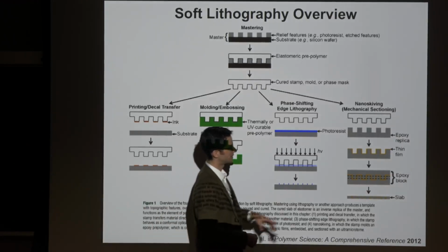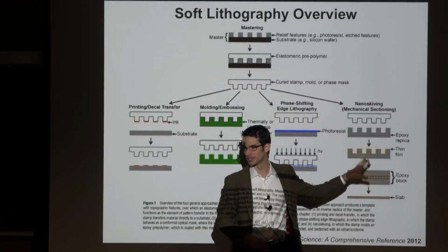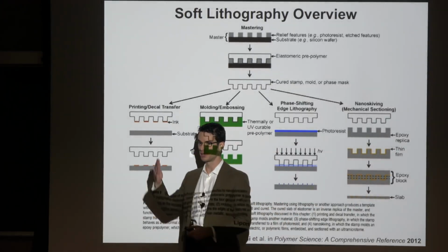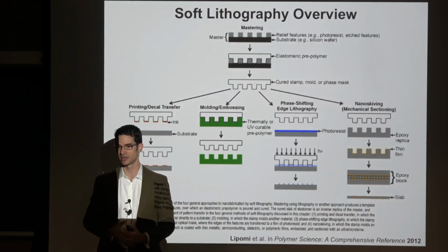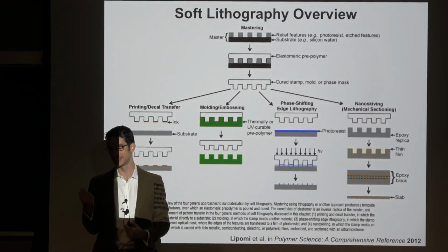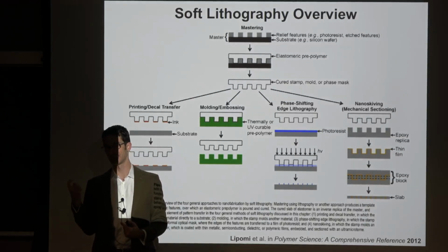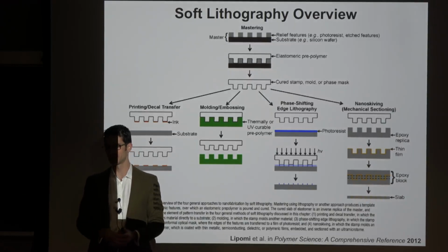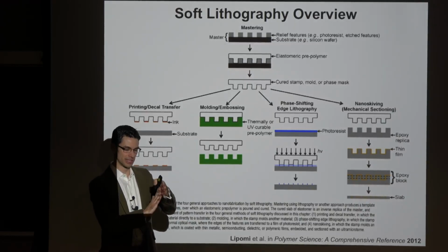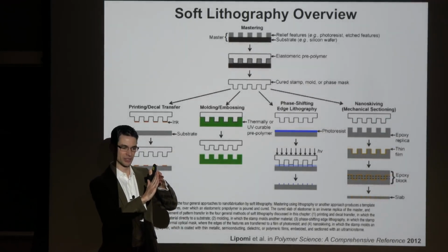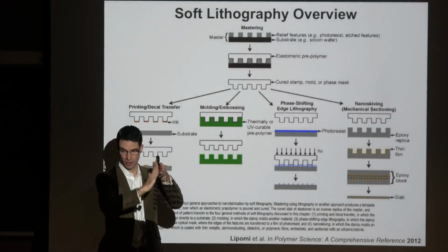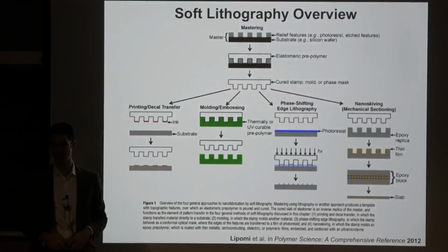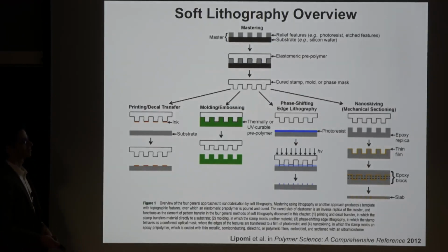This is still just in the research lab, but it's done using a tool called a microtome, which makes structures for transmission electron microscopy. You put the structure in, and the key thing that it has is a single crystal diamond blade that's polished to a 2 nanometer radius of curvature. So it creates a crack tip, which travels up the workpiece, and then a section slides off. It's almost like a nanomechanical deli slicer. Really sharp knife.